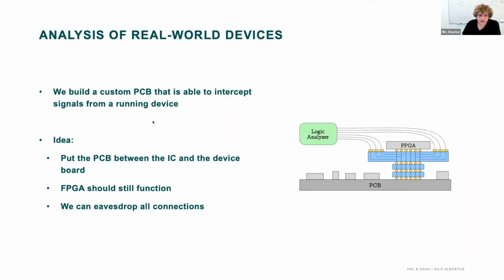So we basically designed a custom PCB that is able to intercept the signals that are coming in and out of the device. So this is the custom PCB that we designed here in blue. And we took out the FPGA that was running on there and inserted our interceptor PCB between the FPGA and the PCB.